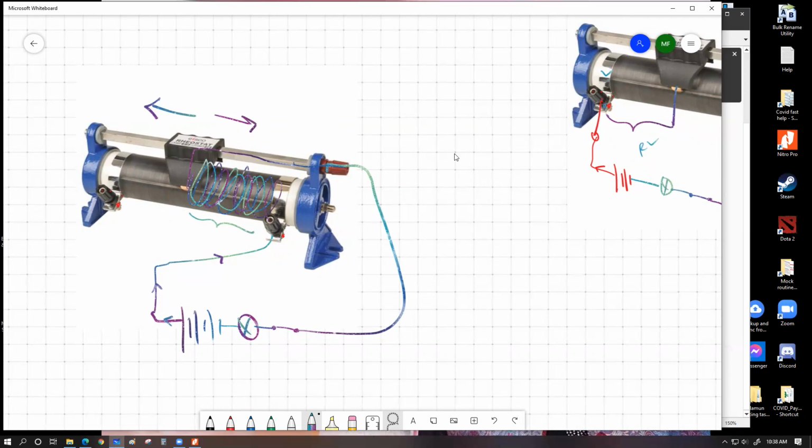So the point to be understood is that if somehow the resistance offered by the skin is penetrated by some charge because of the high voltage, and they can enter into the bloodstream, then they can have a very easy flow path through the bloodstream, and blood goes everywhere in the body, which basically means any part of the body would be accessible for the current to go to. So the question that you asked, why don't we get a shock?